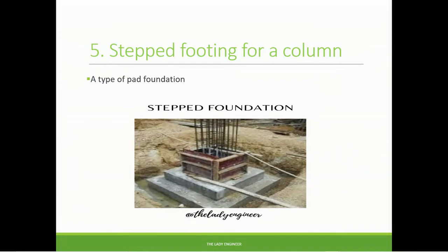So we have the stepped foundation, which is also a pad type of foundation used where the natural ground is sloped in order to minimize the amount of excavation. Now you know when building we use the dumpy level or spirit level in order to achieve a leveled building. So instead of making deep excavations in certain areas because of the slope of the natural ground, you can just resort to using the stepped footing type of foundation.